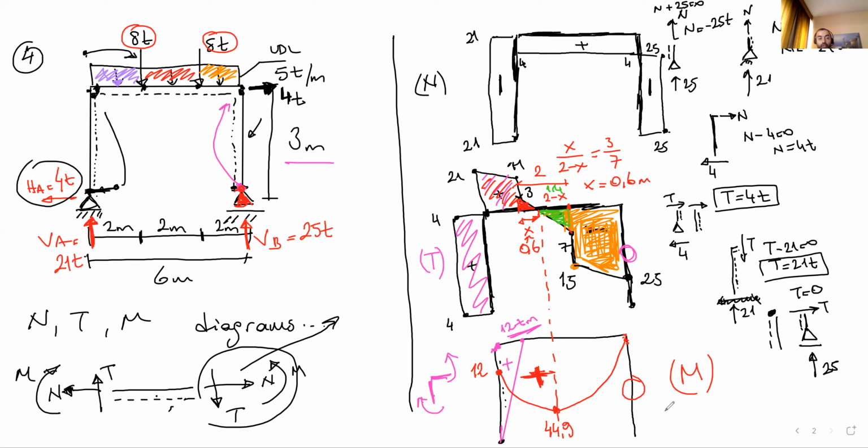By the way, don't forget to draw this portion on your page when you start to solve internal force diagrams. Okay, please draw these positive directions. If you are not sure about the sign of the force, please cut the system over there and write the equation and get the solution with sign.